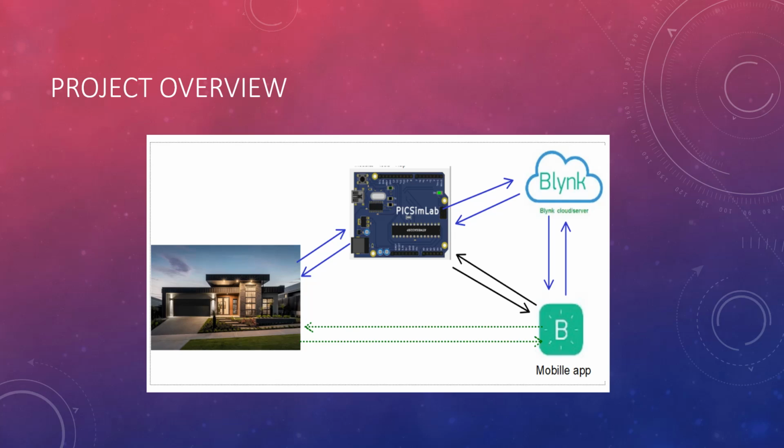So in this project, the home automation system is structured as follows. Various home appliances including garden lights, a cooler, a heater, and water tank valves are connected to the Arduino Uno. The Arduino serves as the central control unit managing these appliances based on the input from connected sensors and user commands. Specifically, an LDR sensor monitors ambient light to adjust the brightness of the garden light, while an LM35 temperature sensor measures the ambient temperature to regulate the cooler and heater. The Arduino is also linked to a water tank system, controlling inlet and outlet valves based on the water volume measurement.